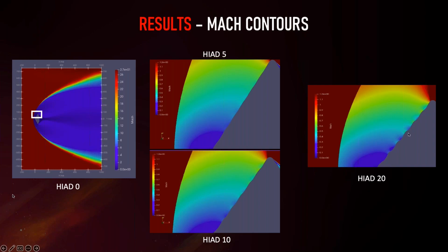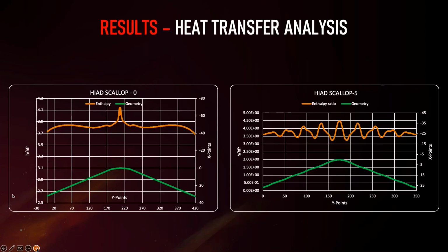It will definitely increase the amount of heat transfer because it produces local regions of high velocity and low velocity, because it forms peaks and valleys, and that will increase the heat load, and that is not something very good. On the other hand, the advantage is the drag, but the disadvantage is the amount of heat it produces. But still, we haven't studied this for Martian atmosphere. We have to study for the Martian atmosphere to find out how exactly it behaves there. The conditions are similar to Earth's atmosphere. That's what we have used right now, because the results we had are all for Earth atmospheric conditions.